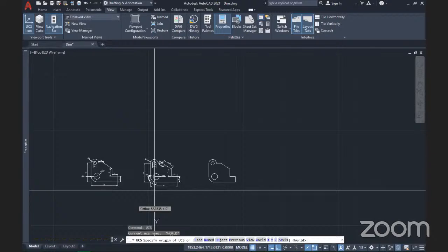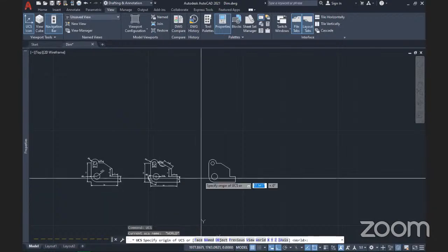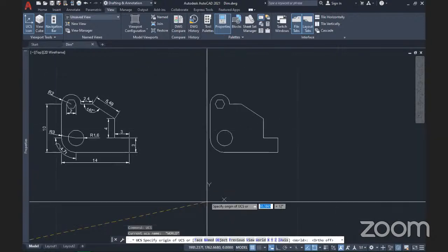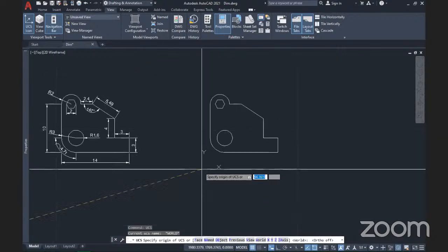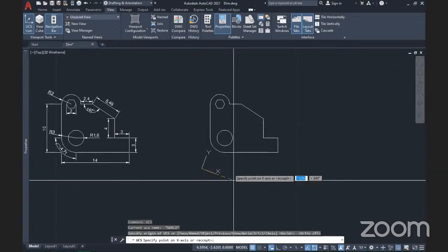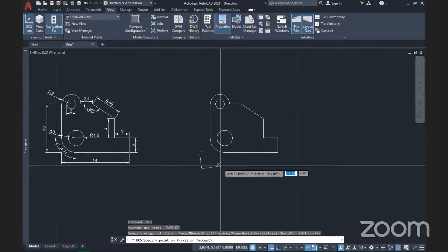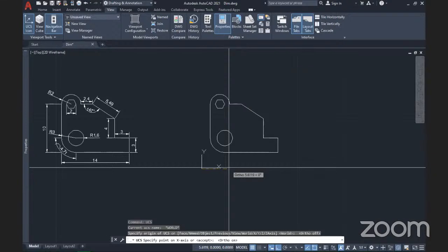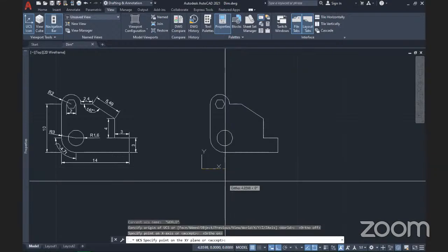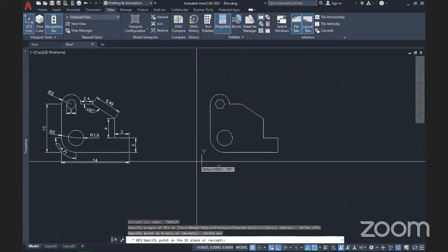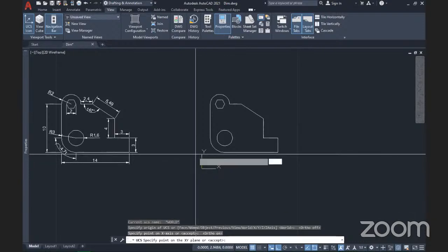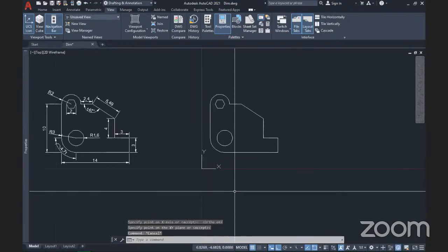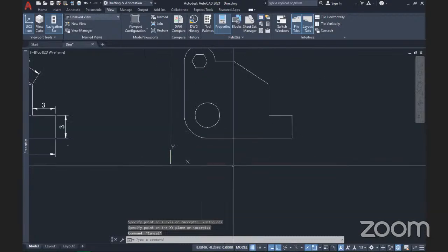Okay. I just selected that. And I'll turn off orthogonal restrictions so I can move it where I want. And I want it to be around here. So, keep it straight also. F8, keep it straight. Okay. And that is it. So we have our UCS icon there.